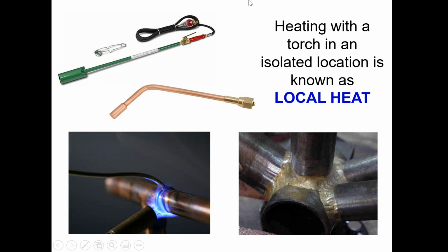These are the flames of choice because it's referred to as soft heat. When you use soft heat, you could actually go in, put the flame on it, and it doesn't concentrate heat. It's not going to turn it red hot in that spot because it's a much larger flame. Oxy-fuel flames, like off of torches like this, will melt through things and flash.